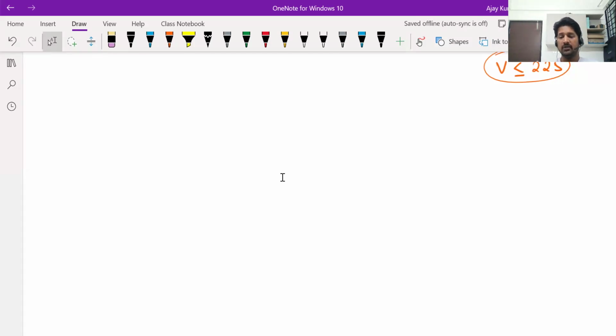Okay. When you apply too much voltage across a dielectric, the electric field becomes so strong that it rips the molecules inside the dielectric and it becomes a conductor. Dielectric is an insulator. Insulator becomes a conductor if you apply too much voltage. Okay, we discussed these examples of also lightning and all. So every dielectric has a maximum voltage that it can withstand, that is called the breakdown voltage.